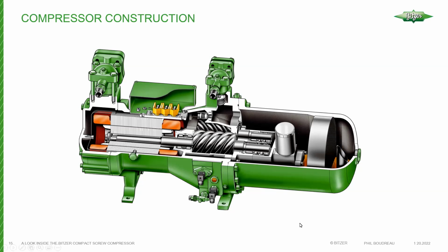So moving on, a screw compressor requires absolute precision when it comes to the layout of the rotors and their distance from each other. The distance between the rotors and the housings is extremely important. These clearances are maintained using good quality bearings.